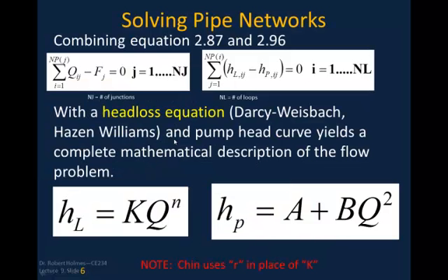So if I look at trying to solve the pipe network flows, I'm going to use these two conservation laws. One is at the node, which says that the sum of the flows into the node has got to be equal to the sum of flows out of the node, from the internal pipes, minus the external flow FJ. And then around the loop, as I just explained, the sum of the energy losses around the loop minus the energy inputs by the pump have got to equal 0.